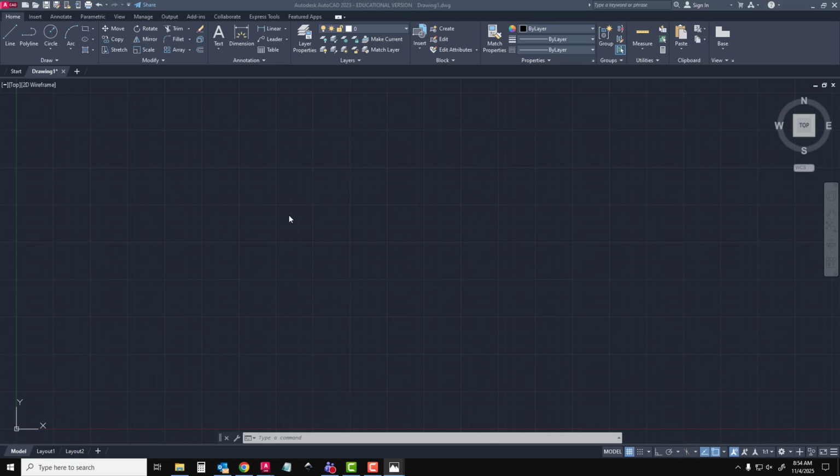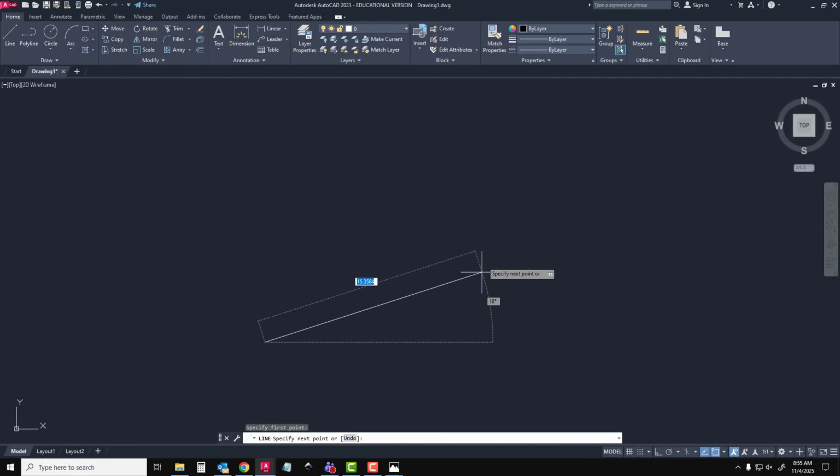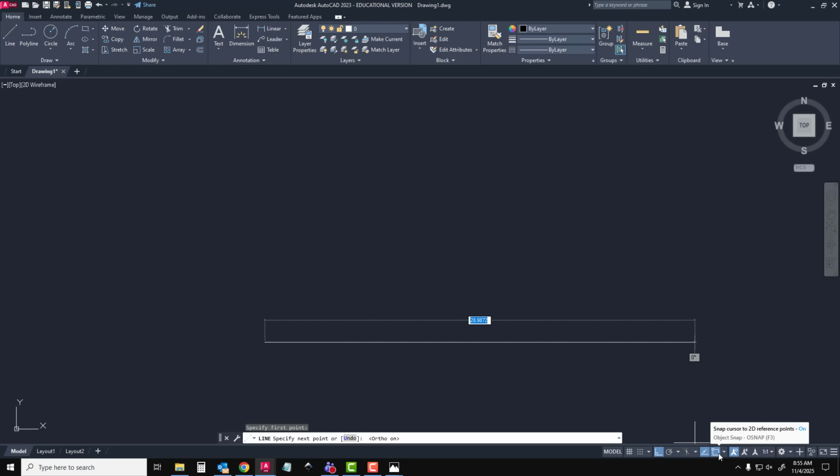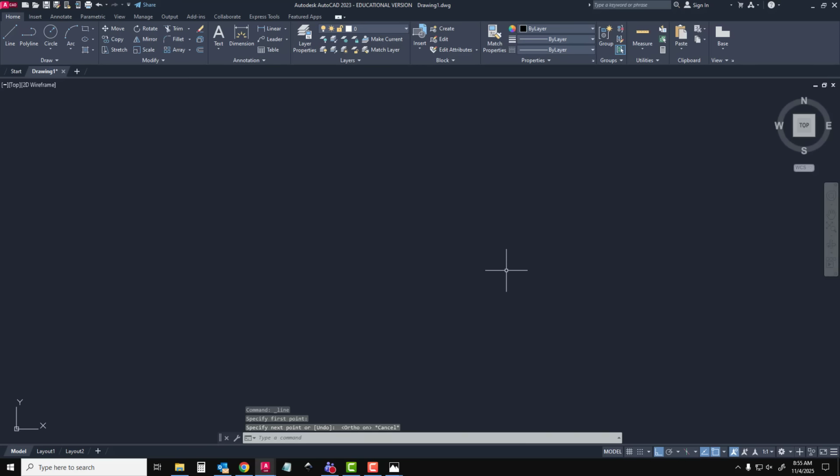The first thing I'm going to do is hit F7 if I want to make a line. If you'll notice, there's no constraint to the angle. If I hit F8, which is this right here, you'll see that now I can only make straight lines. This will help for dimensioning text, and so on and so forth. And then I have some snap modes on right here that I'll go over in a second. So I'm going to hit Escape. You'll see me hit Escape a lot. You'll hear it a lot. It's fine. It's just a way of deselecting.